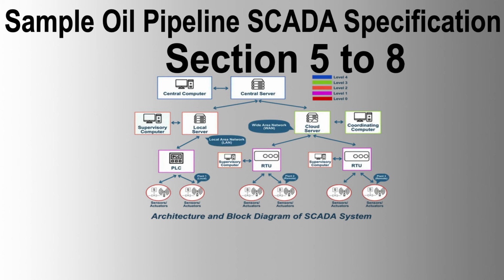6.3 Panel Requirements. 6.3.1 Mechanical Construction. Panels shall be shipped with all components installed and fully wired. Panels are to be built by specialized panel manufacturers. The panel shall be installed within an air-conditioned building with a false computer-type floor, supported via a subframe bolted to the floor. The panel shall be constructed for installation at floor level and provided with a 100 mm by 50 mm plinth, continuous throughout the entire length of the panel.